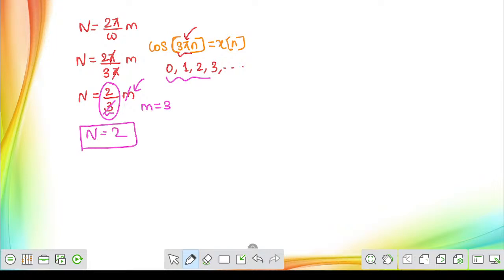So in order to obtain the proper integer fundamental time period of any given signal in discrete domain, we will have one more integer factor here, that is called m. For that m, you cannot choose any value. You will have to choose the minimum value which will cancel the effect of the denominator. If the denominator is 3, I will choose the minimum value 3, such that 3 will get cancelled. The fundamental time period of the signal will become 2 seconds. Understand, sir? This is how you have to calculate the fundamental time period of any signal when you are doing these things in discrete domain.